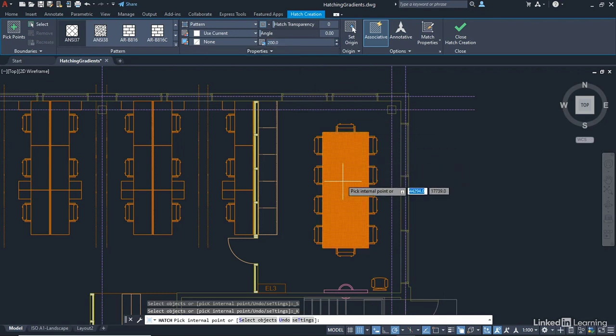And then when I come in here, you'll see, can you see it's starting to get a little less sort of dense there? So we just need to keep increasing that number until we get a hatch pattern that we're happy with. Now, hatching is a bit of a black art, to be perfectly honest. It's one of those ninja skills that you need to learn. So 500 is looking reasonable.